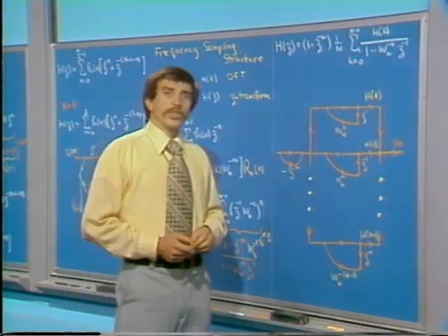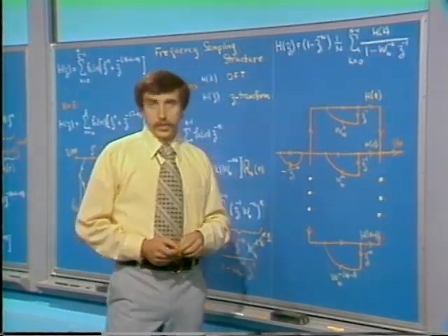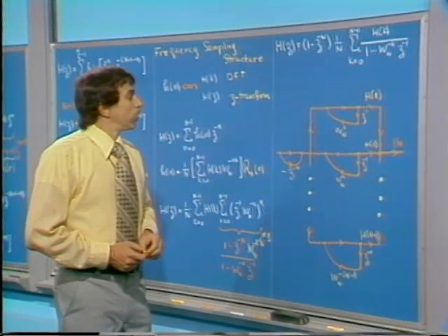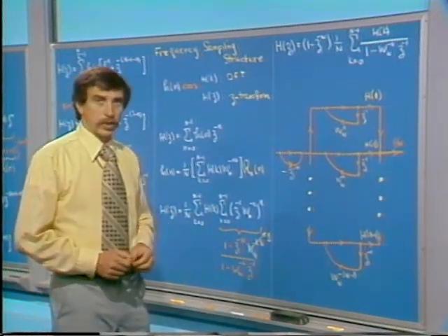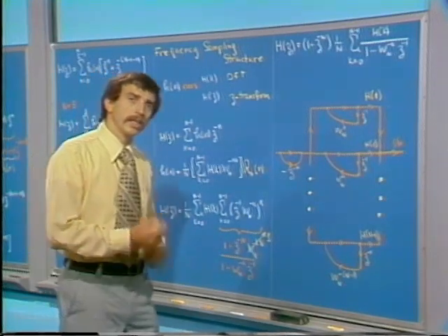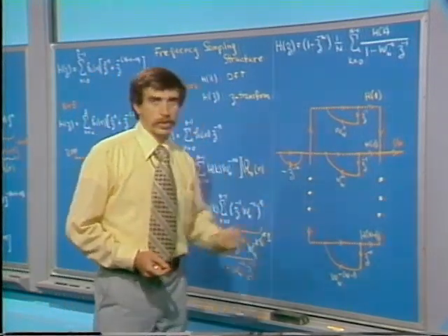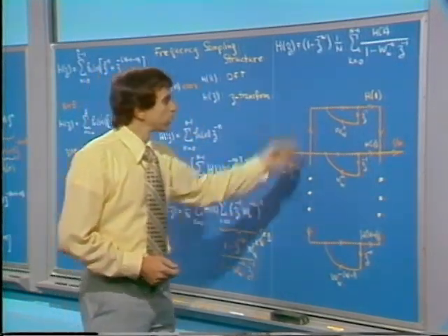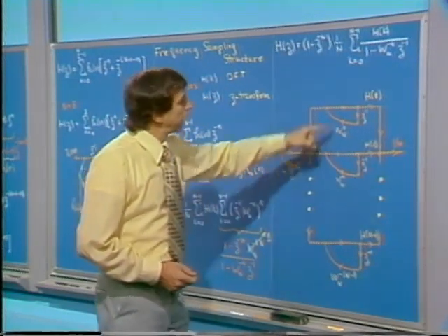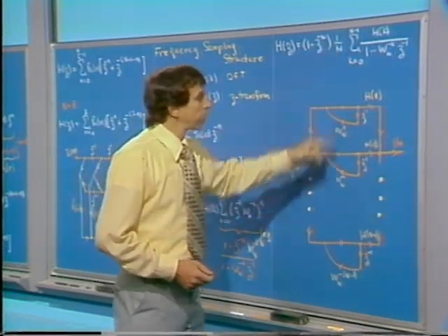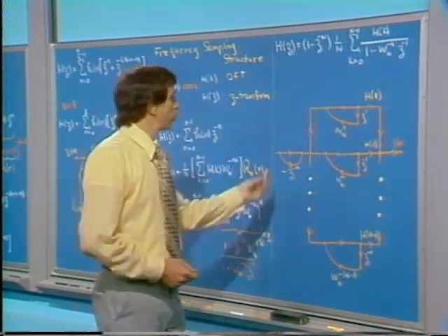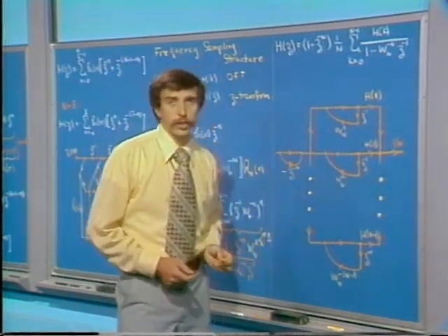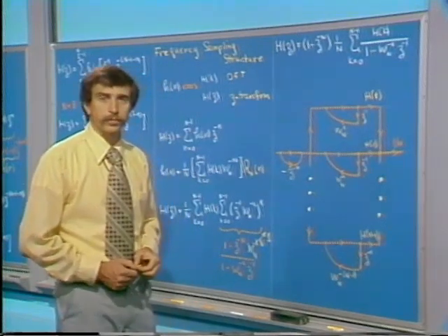First of all, we started with a finite impulse response system. Obviously, we've ended up with a finite impulse response system, but the system appears to have some poles in it. That is, it's a recursive structure, and it has, in fact, capital N poles involved in the implementation, although presumably the overall system function has only zeros.